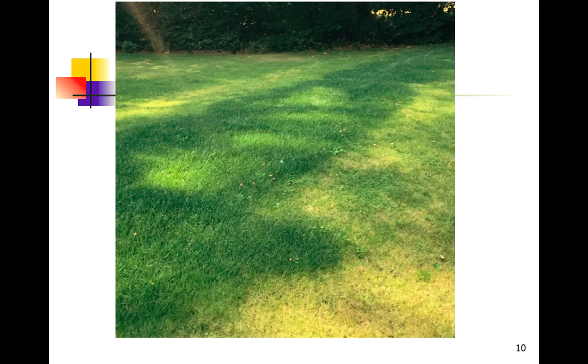After about 1 year of the Oscar being in use, you can see lush green grass growth over the top where the coils are. This is just sand with the coils and low flow effluent being dosed to it. You can tell from the green growth patterns the amount of nitrogen that's being taken up from the waste stream just in the grass growth.